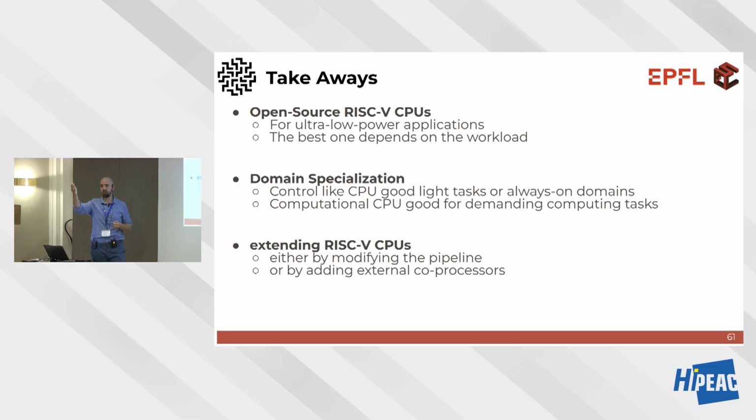There is CVA6, which some of your colleagues mentioned. That is also from open hardware, but it is application-class, so it's not very often used at the edge for data processing. As this class is tailored at the edge, we skipped that CPU, but that CPU can run Linux, has memory protections, has 6 pipeline stages, out of order, superscalar, and can do many more things. Of course, it's bigger and consumes more power. There are other Verilog CPUs, VHDL, and so on.